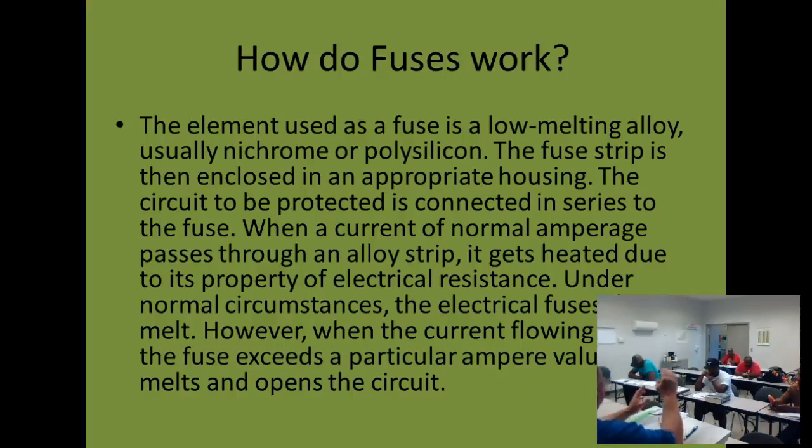You might want to select a range depending on what you're ohming. But trust me, none of these meters, if they're not touching, are strong enough to read across a gap of air. Okay? And so that means what it's telling you is we don't have a path. That's all they're telling us. We don't have a path.